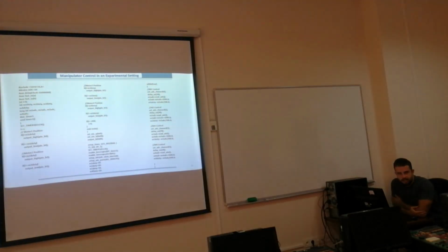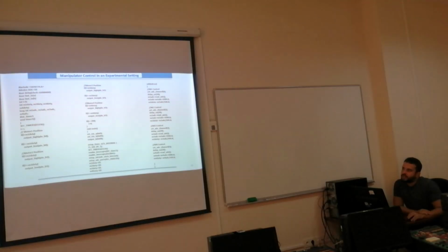We can see our CCSC compiler code for this project, this workshop. Firstly, we include the code for our microcontroller, then we specify our analog digital conversion bits. Then we can see the function for timer 1 interrupt. In this interrupt, we use set timer 1 value to get our 0.1 millisecond interrupt time. Then for 4 different motors, we have 4 different function blocks to control the PWM signals. You can see them in the code.